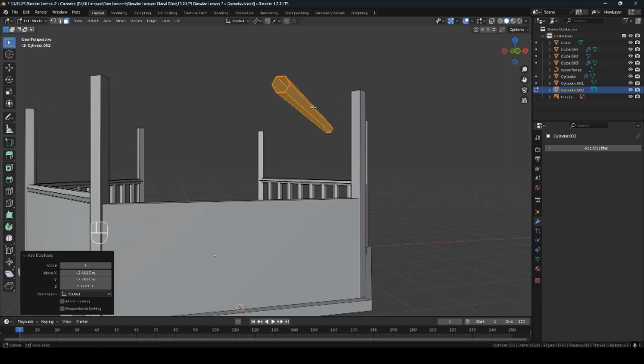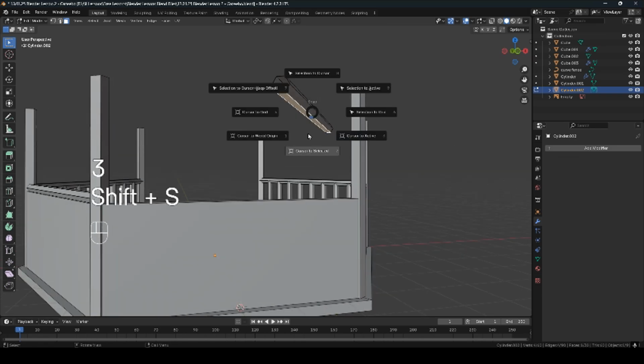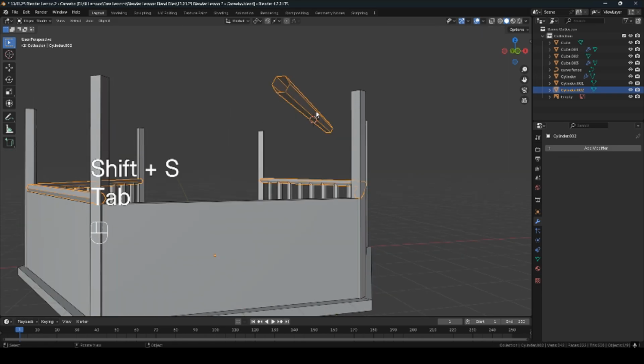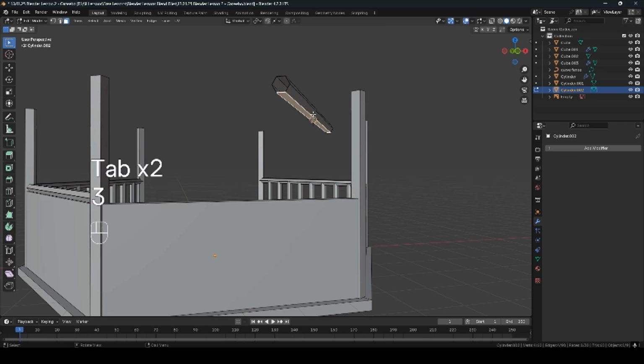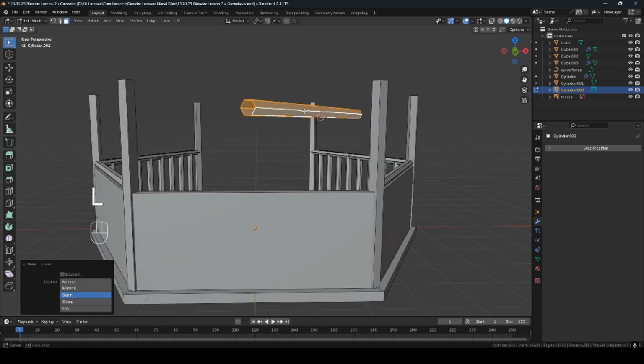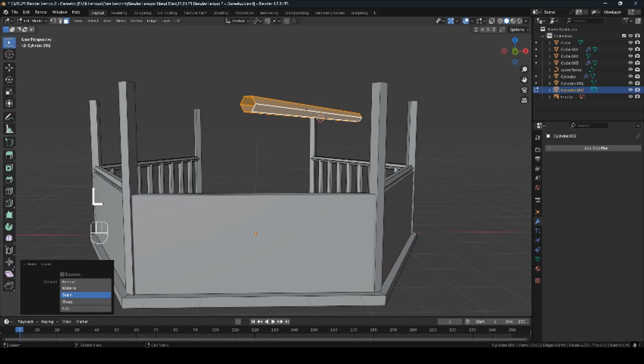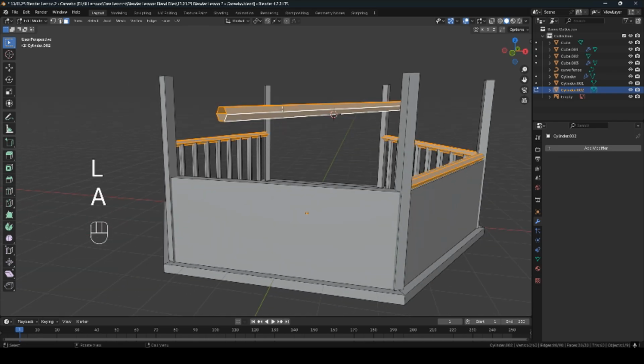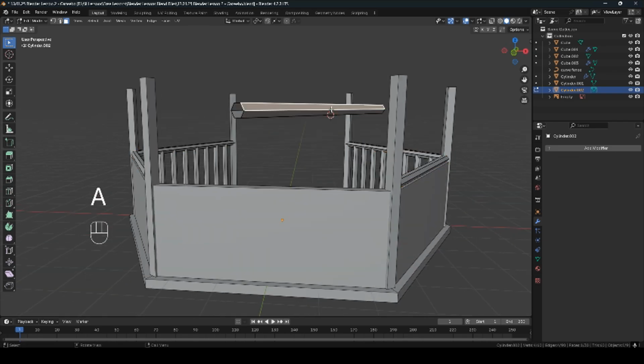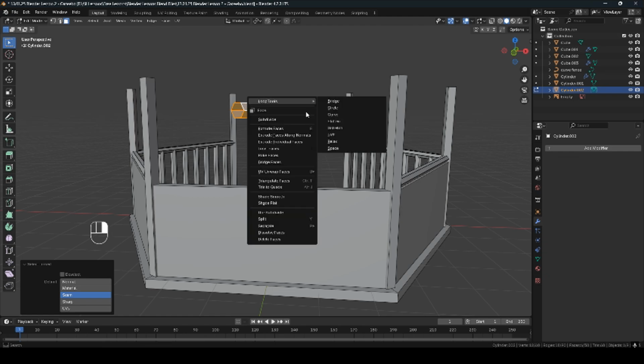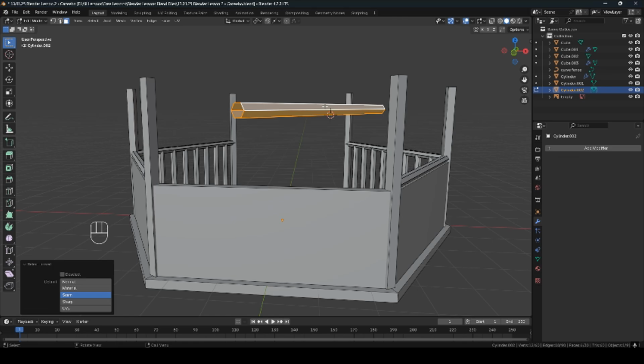And again, we want to put the 3D cursor underneath, go into object mode. Actually, reselect this again, not A to select all, but hover over and press L. If you do press A, you'll select all of them, but we want to separate this. So again, press L using your cursor to hover over the top. Press P to separate your selection.